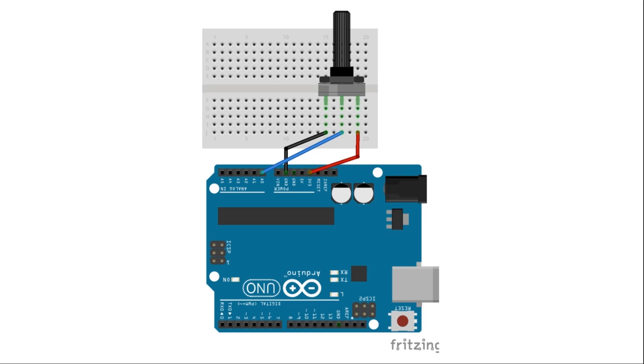Finally, we have got the last wire connecting the 3.3 voltage on the Arduino board and the first pin of the potentiometer variable resistance. If you don't have a variable resistance, you can try the same setup with a fixed resistance or without connecting any peripherals to your Arduino, and the exercise will still work. Let's go to the coding part.